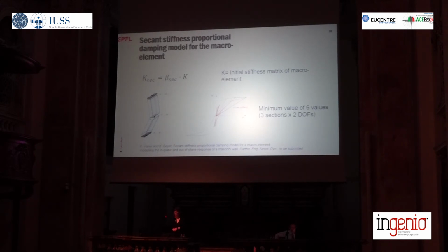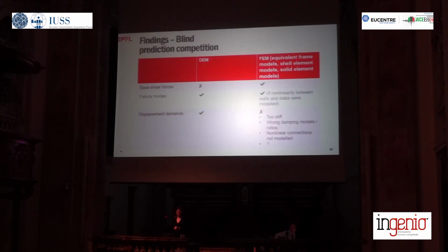So just to summarize quickly the findings from the blind prediction competition, if we compare very broadly, then we can really say the discrete element models have really performed well in terms of failure mode and displacement demands.